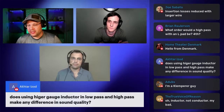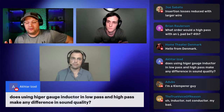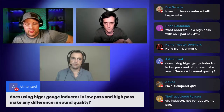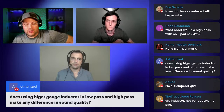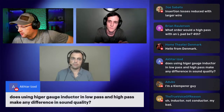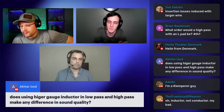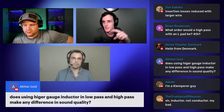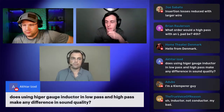Now, the other thing, and by the way, in crossover simulations, a lot of people don't realize this. For example, XSIM, which we all talk about using, you can put the DCR in and it will show you how that might change your inductor. You can pull that up in the specs of a Parts Express page. It'll give you the DCR, and that's labeled ESR within XSIM, equivalent series resistance.